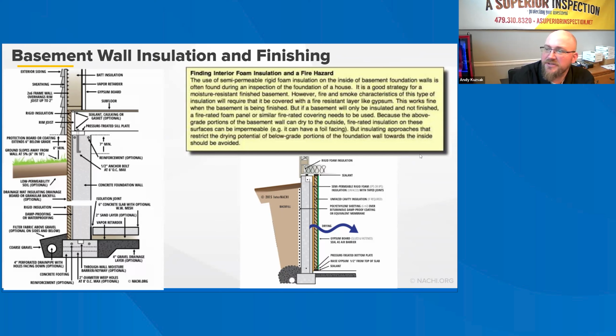Interior insulation approaches using foam, which offer good moisture performance, require a fire-resistant covering such as wallboard, making them suitable for finished basements but ineffective for merely insulating unfinished areas. Experts in the industry have different strategies for basement finishing. A successful basement finish design must address exterior waterproofing, humidity control, and air sealing properly.